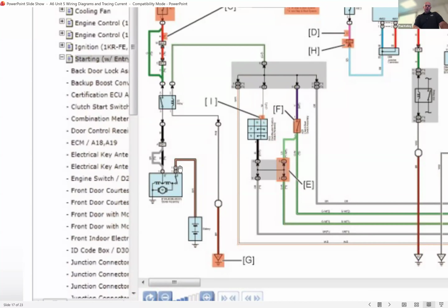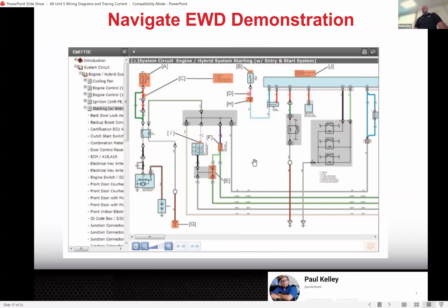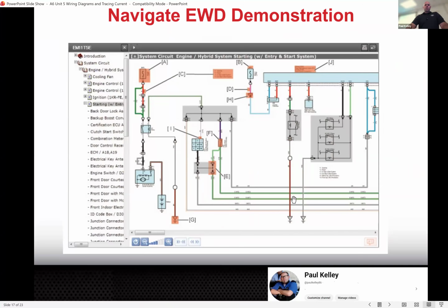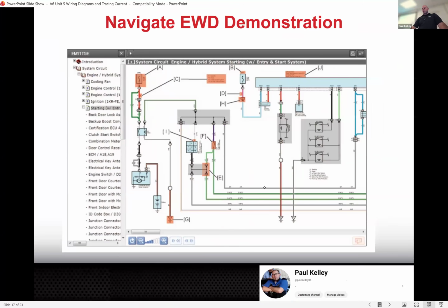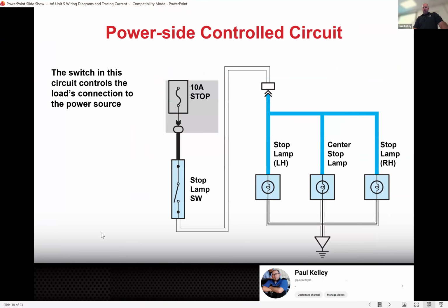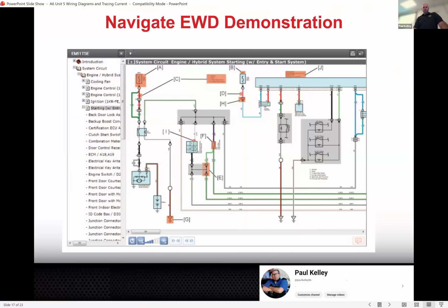That's the big positive battery terminal. And the ground is right here on the case. And then this right here is a starter relay. So this is the small solenoid wire, right? So if you wanted to diagnose something, you got to sort of know which diagram to go on. And then sometimes the diagrams are interactive and they can give you like connector end views and whatnot. And if they aren't, you got to dig them up. So I'll show you some examples of that.